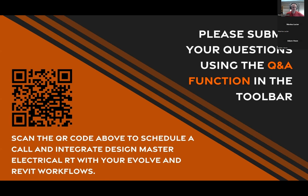You can select the graphic. So you have to select the family that's going to show up in Revit. You have to choose the graphic that's going to show up on the one line. I can put this panel in. I can connect it to another panel. So you can start building out your one line, just drafting it on the one line without thinking about your model. If we go highlight this device, you'll see that it actually did create it in Revit,